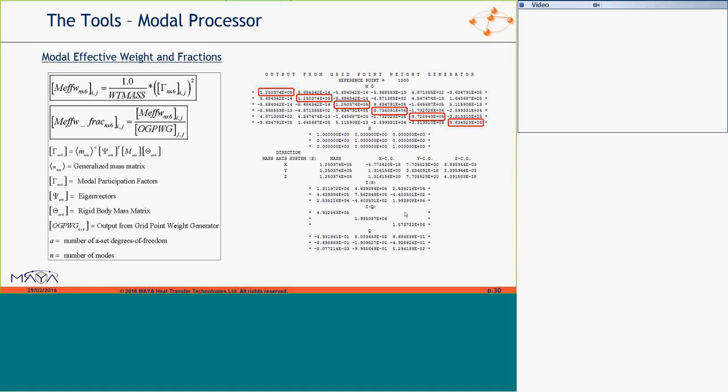And talking mass and weight, we use weight here because of WTMASS, the weight mass parameter in Nastran. It's essentially mass to weight if you want. It really scales the mass matrix, but in the preprocessor it allows you to define your units of mass and all mass-related properties as weight.